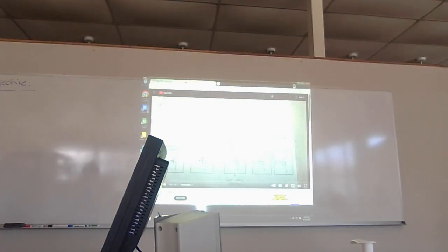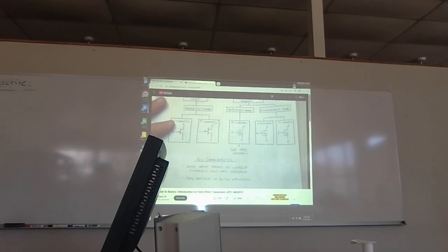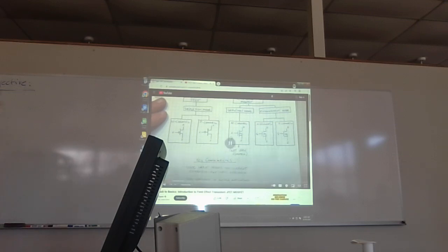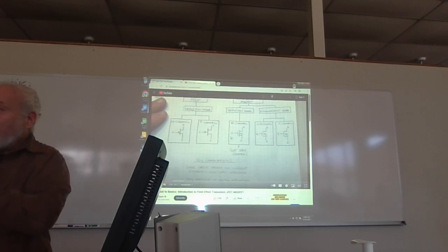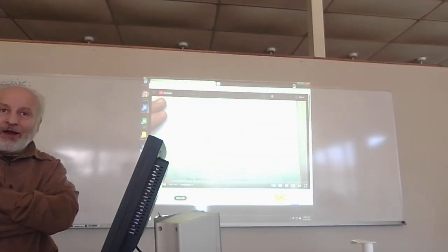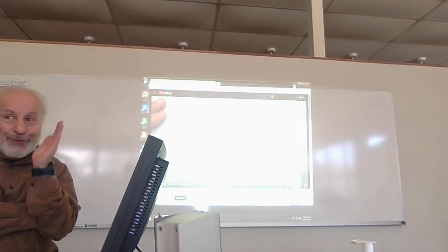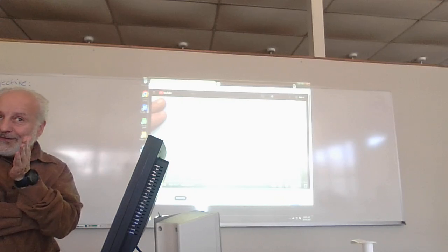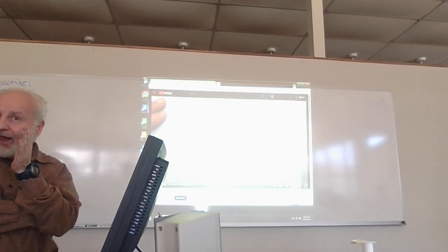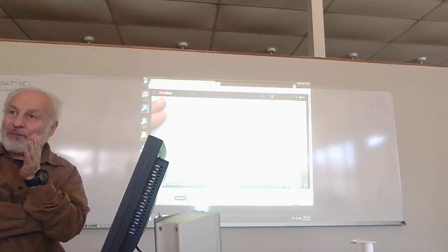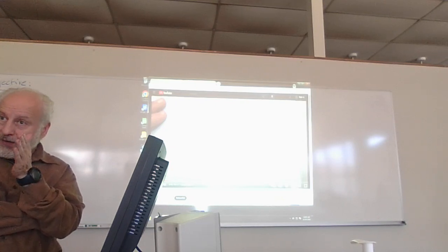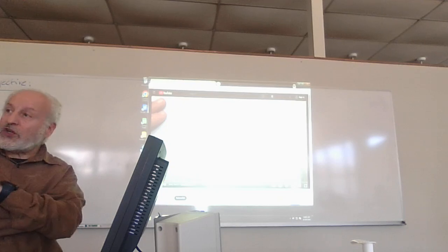Now, regardless of what we're talking about in terms of FETs, they all have some key common characteristics. The gate input draws virtually no current, just a very, very small amount of leakage current, has a very high input impedance, and they're typically very efficient in switch applications. Two very important points. Why would I want to use this stuff? One, the input impedance is extremely high, looking at it from the gate. You with me so far? The input impedance of this device in AC or DC is going to be very high looking at it from the gate. Got it? And they're very efficient for switch applications.